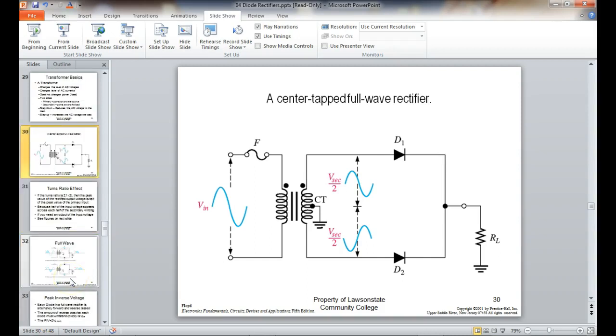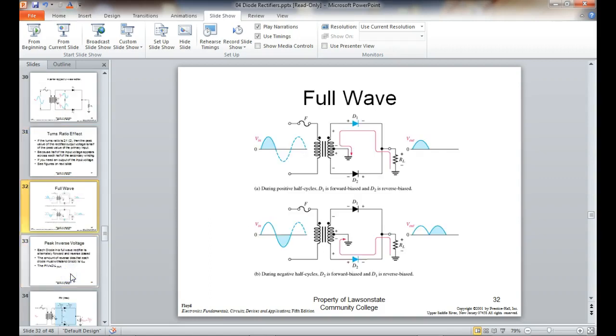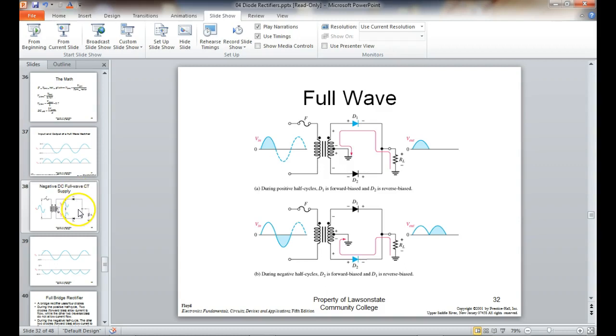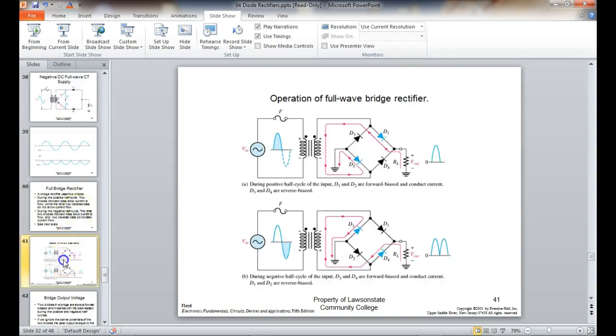Now on a full wave bridge, we get the entire voltage of the primary. And of course it depends on how we do it. We're going to show y'all some neat tricks. And of course here, when we do this, we have to take out 2 diode drops. So with silicon, this output peak would actually be about 1.4 volts less than the input. That makes sense? Are we okay?